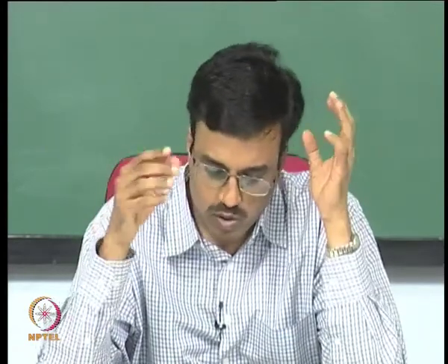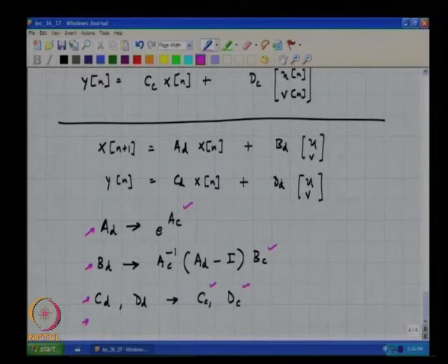One way of doing this is to deliberately assume that the loop filter is sampling at a much higher sampling rate than the quantizer. You understand? So, instead of assuming that the loop filter samples are needed only at 1 hertz, if you say I will compute the loop filter samples not at 1 hertz, but at say 32 hertz, which is still better than computing the loop filter output for all time and only taking one sample.